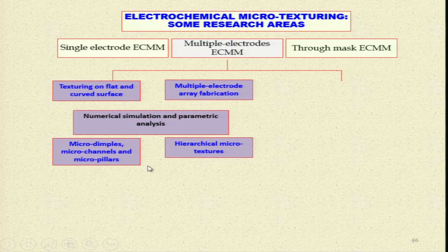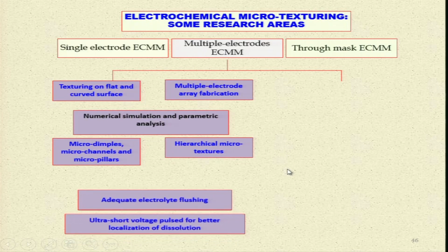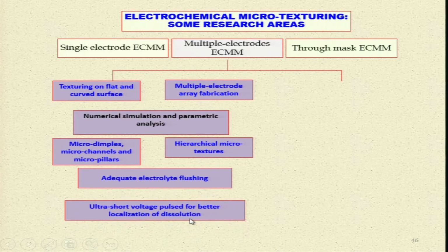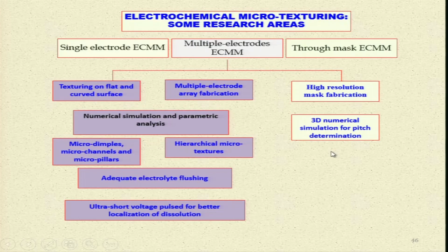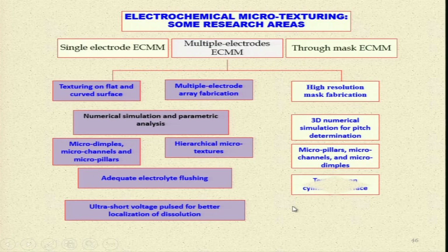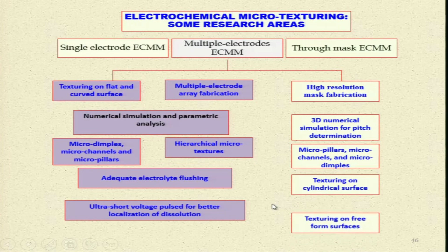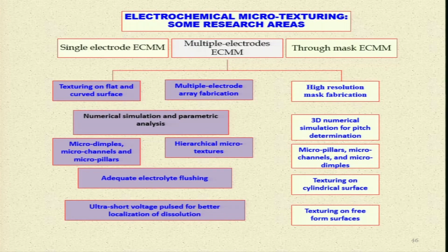All this we have already discussed, and I am trying to show it here to you. And adequate electrolyte flushing, ultra short voltage pulses for better localization of dissolution, and then high resolution mask fabrication, 3D numerical simulation for pitch determination, and micro pillars, micro channels, micro dimples, all of them have been created, and I have already shown to you. Textures on cylindrical surfaces have been done using this particular process, and texturing on free form surfaces also has been done, especially for the knee joint and hip joints.